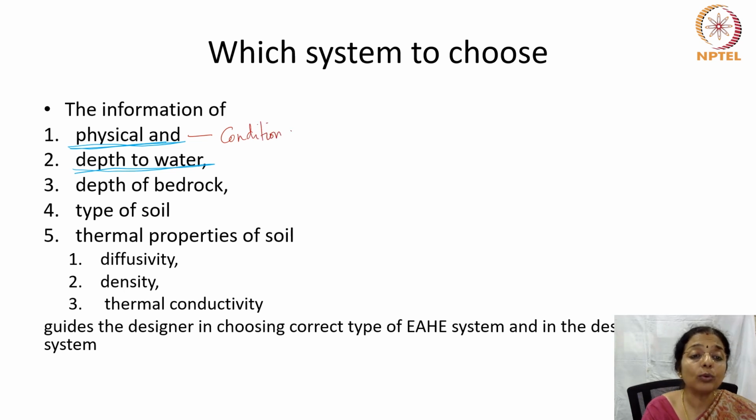We need to understand the depth of water, because what will happen when you start digging if the water table is very high? You will start getting water when you start digging. Then how can you lay the pipe? So depth of water is important for us to understand. Third is depth of bedrock. Suppose you are digging and you end up hitting rocks or a quarry area, then how will you lay the